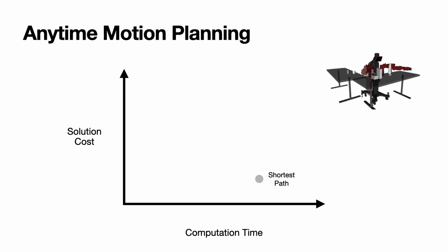In motion planning, finding the shortest collision-free path can be computationally expensive. This has real consequences in many robotics applications. So when these systems have hard time budgets, they're often willing to accept any collision-free or feasible path. This can be computed in less time, but the solution usually has higher cost. In practice, what winds up happening is that the system finds a feasible path quickly, then uses the remainder of its time budget to progressively find better ones. This is what anytime motion planning is all about.